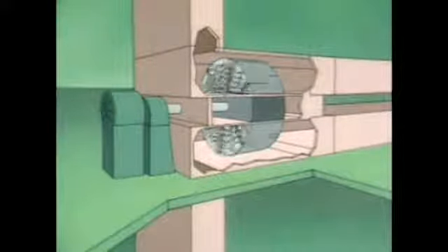The heating surfaces rotate through the hot combustion gases. So, in this section, the heating surfaces are warmed by the hot gases. Then, the rotating heating surfaces transfer heat to the cooler air flowing to the boiler. The warmed air is sent to the boiler's combustion area. With this design, heat that would otherwise leave through the stack unused preheats the air entering the boiler, so the boiler operates more efficiently.